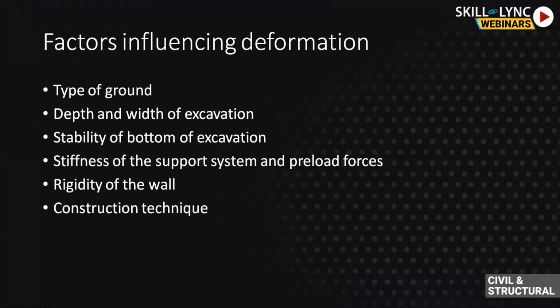We can bore walls like secant pile wall and contiguous pile wall, but beyond that there is a vertical tolerance, so we should be careful. Diaphragm walls need some special equipment to drive. Generally, for other walls like soldier pile wall or sheet pile, 10 to 15 meters is the maximum. Going deeper is not practically possible.